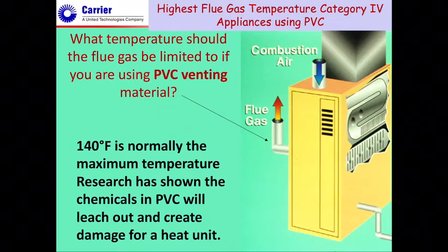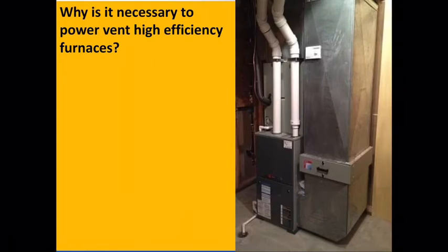Now, there's no guarantee that it's going to work. There's better alternatives out there. PVC would not be the one to use. For a normal residential condensing furnace, in most cases, it's completely acceptable and it works fine. But there are applications where it's probably not the best fit.